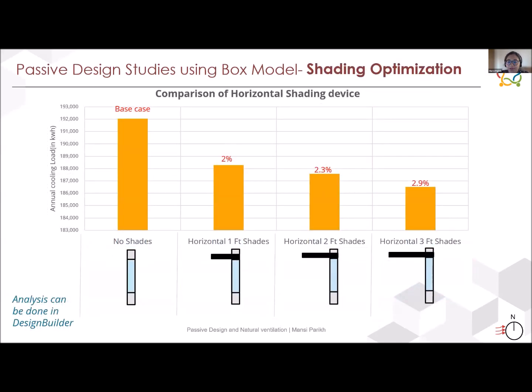After the window to wall area ratio studies, we started looking into optimizing shading devices for this particular building. This study assisted in showing the clients and architects the importance of shading devices in reducing the energy consumption. So 4 cases were studied for the east-west longer axis case with 30% WWR.